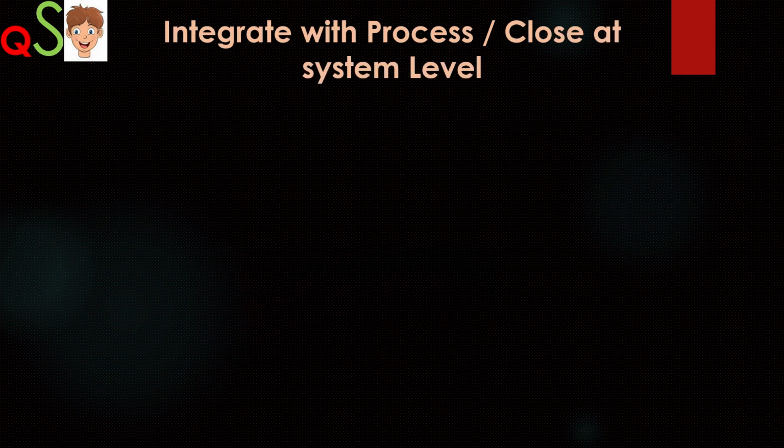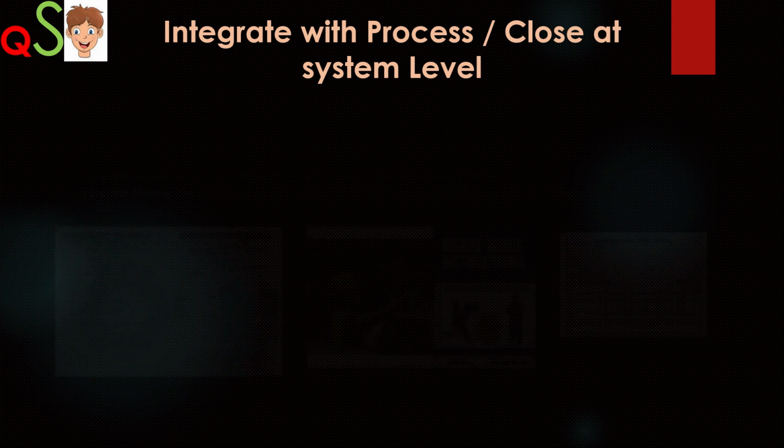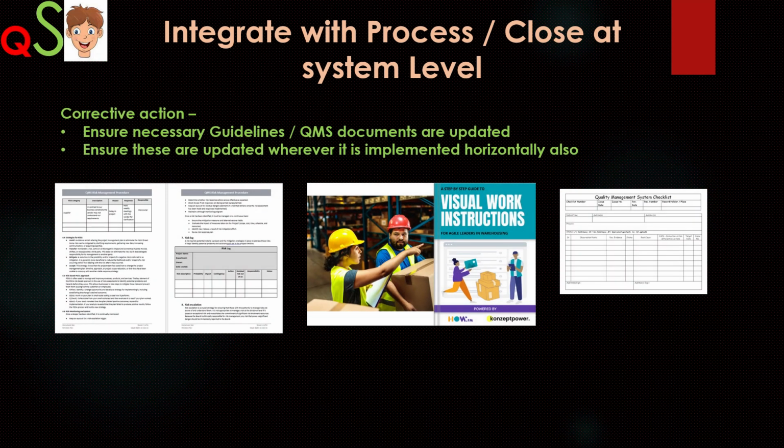So in this example, the oversized pin produced during setup trials got mixed up with regular production pieces and reached the customer. The solution devised must involve revision of guidelines for handling and disposal of setup samples, which may bring in better identification methods, segregation, and disposal, scrapping of these pieces.